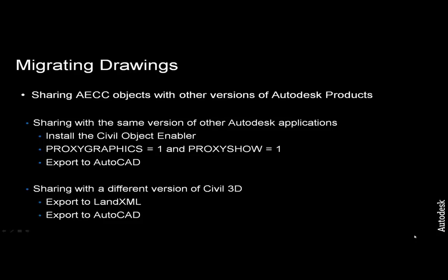However, it is important to note that they will not retain their styles, so some manual effort will be necessary to get the drawing looking like it did in the prior release. If, however, the civil intelligence is not necessary, you can again use the Export to AutoCAD command to explode the drawing and save it as a primitive AutoCAD drawing.